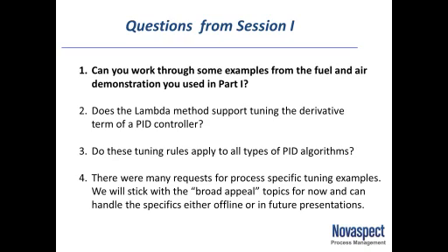Go back to the 1970s or so. Most pneumatic controllers of the time and most first-generation digital controllers back then used the series PID algorithm. You might also hear series called classical or interacting. Now the difference between the standard and the series is in how the derivative term is handled. So if tuning a PI only controller, as we will in all the examples today, then standard and series become identical. The difference is just in the derivative. So with PI control, the rules I'm presenting here can be used for either standard or series and will work for almost all of you out there.